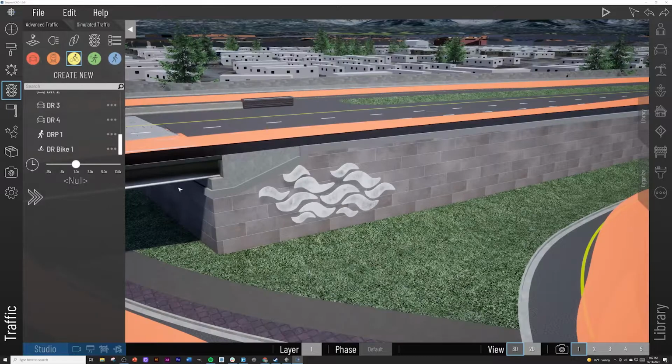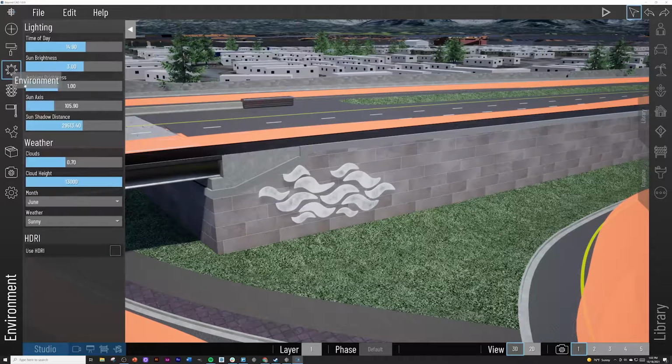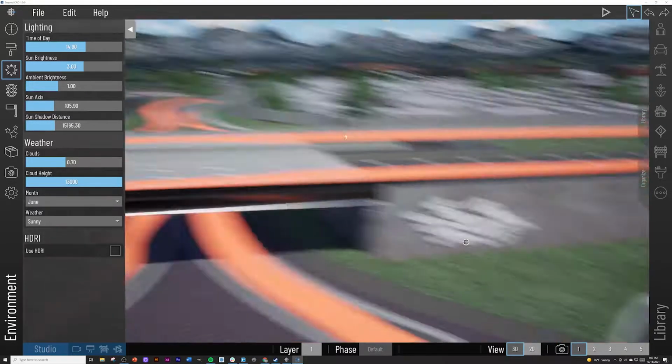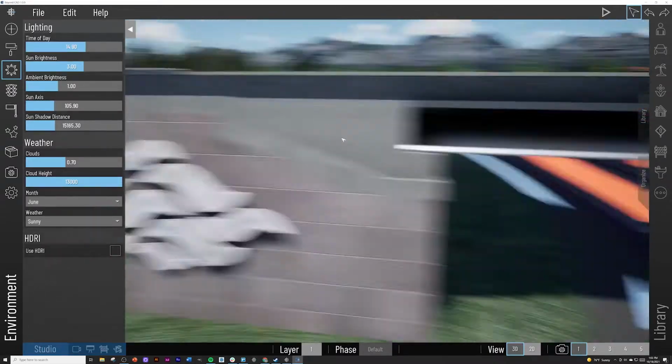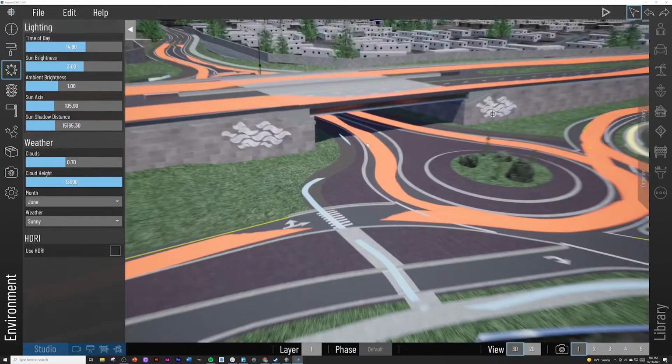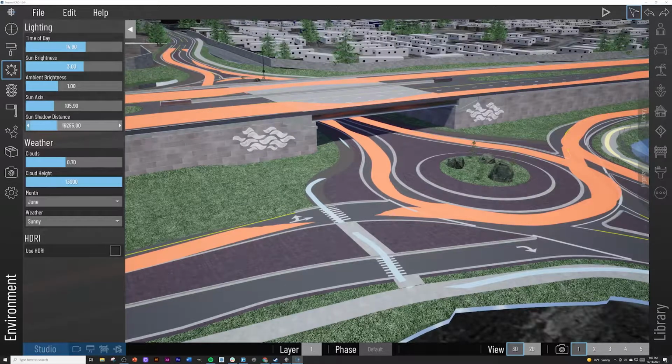All right, and we're going to do path cameras because they're very important. But before we do that, let me just... So with shadow distance, it's an interesting thing. If you do it too far, you'll get shadows way in the distance, but the close ones won't look as crisp. So you've got to find that balance where you want to show the crispness of your up close shadows while still showing the ones in the distance. So if our camera's going to be out here, something like that.